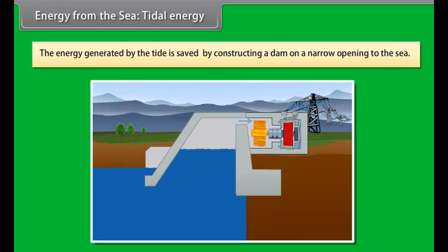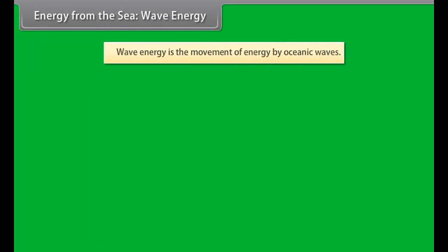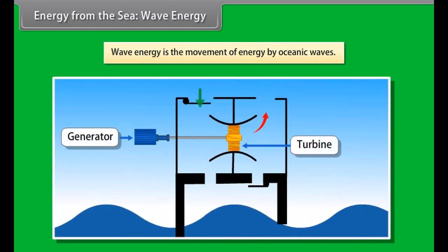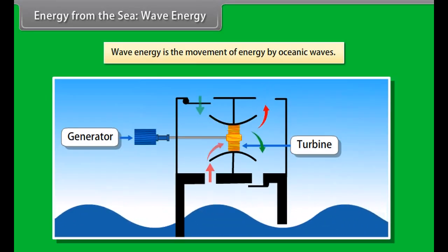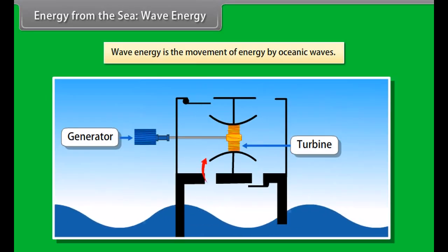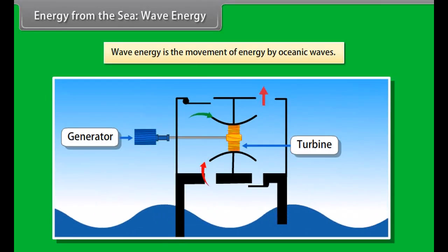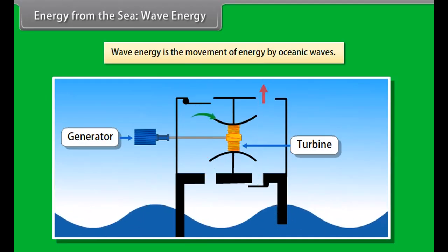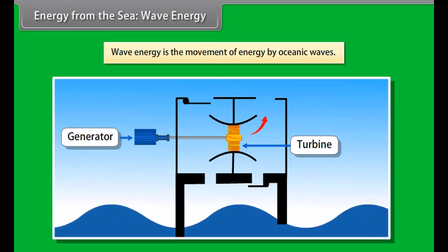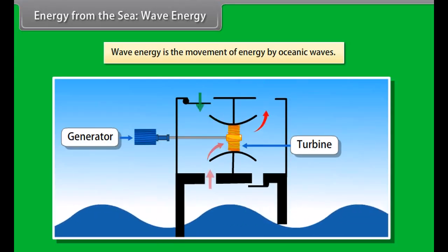In low geographical latitudes, the domestic hot water usage is provided for with temperatures up to 60 degrees Celsius by solar heating systems. The most common types of solar water heaters are evacuated tube collectors and glazed flat plate collectors, generally used for domestic hot water, and unglazed plastic collectors used mainly to heat swimming pools.